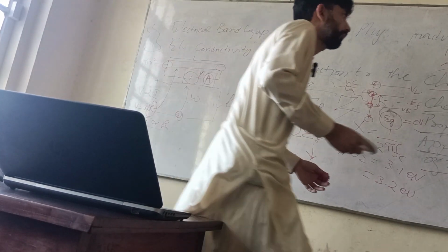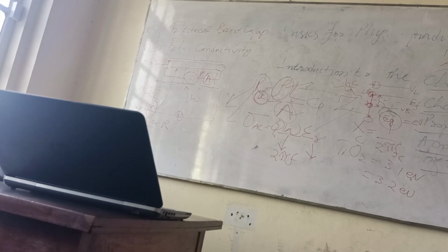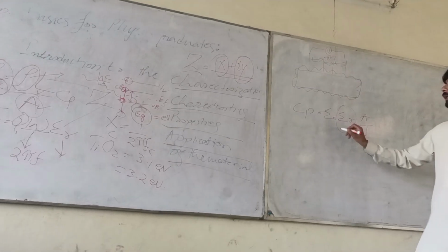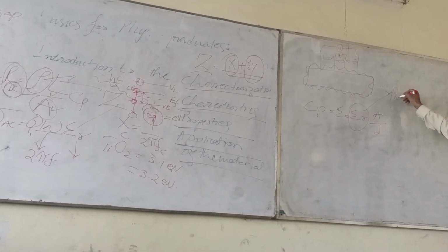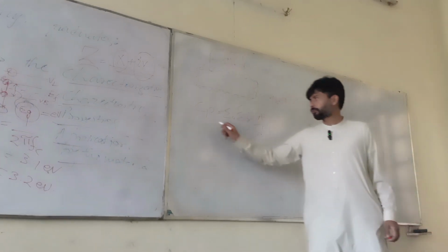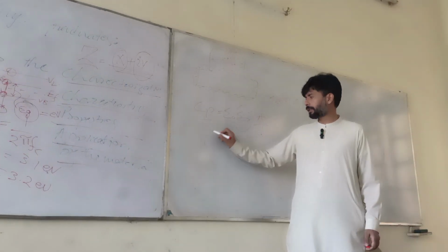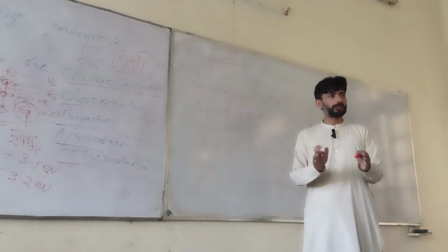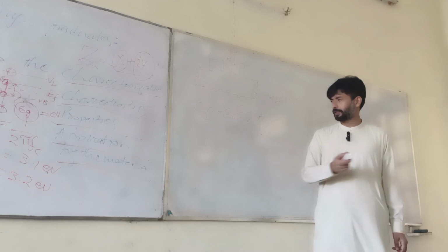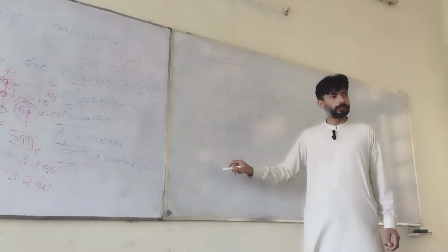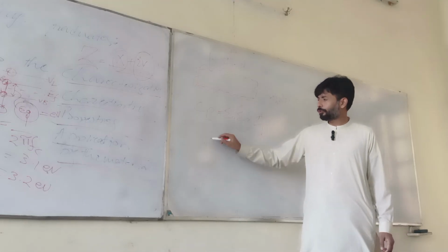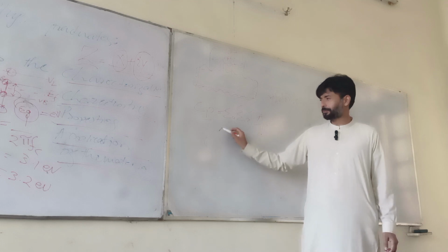For example, if you know the capacitance, you can derive the relative permittivity. This, for example, is your figure. It is just like a capacitor, the final product of your powder processing, and it is coated on both sides, silver coated, gold coated, or whatever. So you know the diameter of this metal, the thickness of this metal.